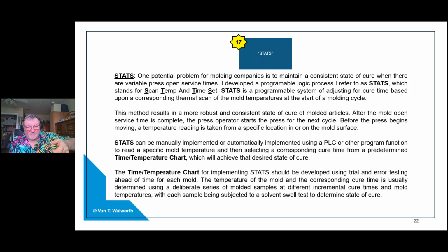It might be with an infrared non-contact, or it might be with a contact that is on the press, usually on the top of a core, on an edge of the mold right beside where the cavities are. We pick a spot. Especially with infrared non-contact, those often read slightly incorrect because of the reflective nature of the steel. And so by creating a little patch on the mold that is roughed up, like a little bit of a texture to it, and then painting it black with a high temperature black paint, I can take the temperature of that with an infrared, calibrate it to an offset, and actually know what that temperature is and have a consistent temperature.